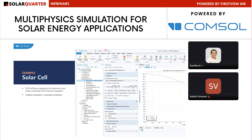So this is a screenshot of the COMSOL Desktop interface. I will also explain the desktop interface in detail when we do the demo. Here I'm showing the screenshot to address this example of modeling a solar cell. Irrespective of the physics, the workflow is going to remain the same when you are using the COMSOL tool. So first you will define the parameters that you require to model your geometry.